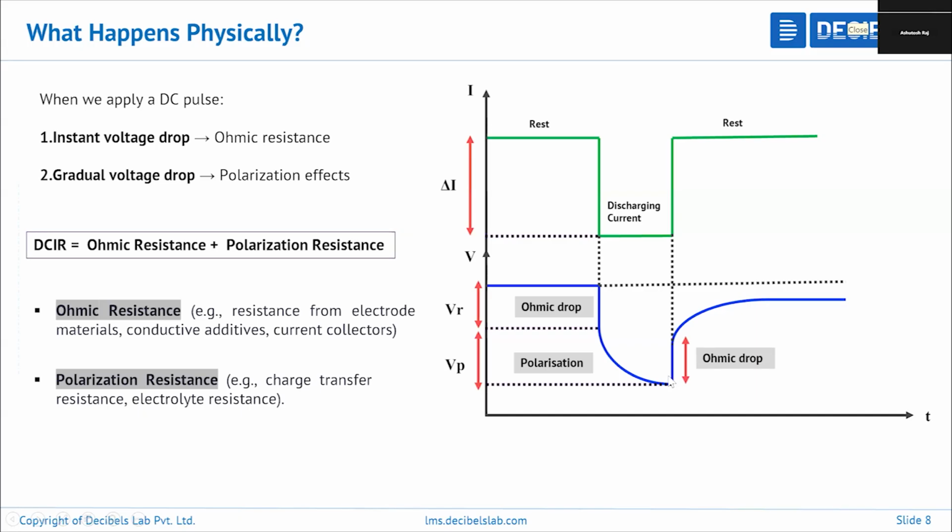So, in these durations, you can extract the parameters, because you can see here our cell has reached our desired SOC, and at that desired SOC there is not that much change of SOC. So it will be accurate to extract the parameters from that region.